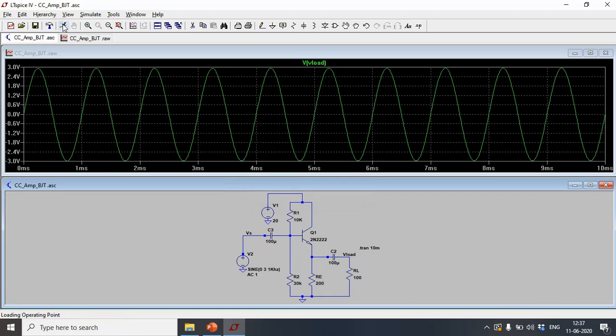See, again you are getting it. So this is how for different load conditions the values differ. If you are going to design it for a 100 ohm resistance, accordingly these values will change. But if you do it like this, it will constantly sink more current, and it will get heated up and more power will be consumed. So you have to judiciously choose these values depending on the max load conditions.